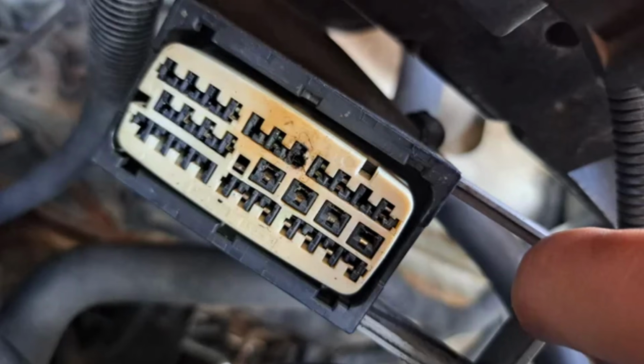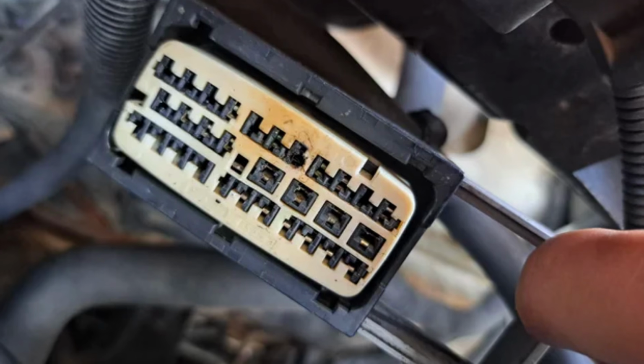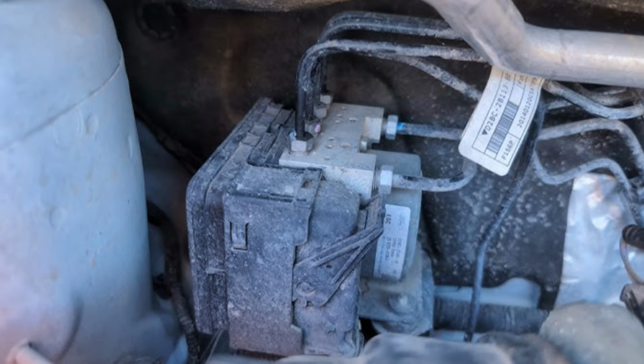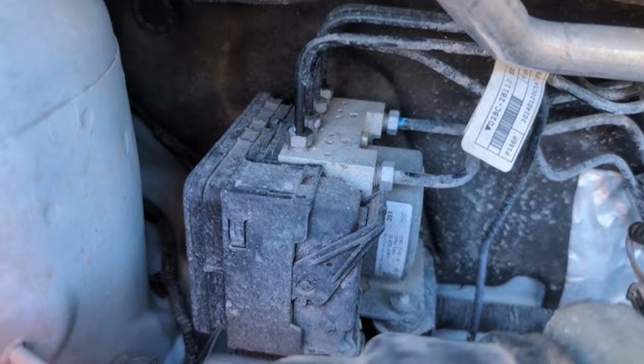Then it makes sense to have a look at the ABS module connector. Sometimes it may be loose or affected by water. Any corrosion on the pins means that you need to clean it properly or have a car electrician clean and check the system. Unfortunately, wiring may fail in other spots, like the wire connecting the ABS sensor with the module, or the harness connecting the ABS module with the PCM or ECU, etc. In such cases, you will need professional help to find the defective spot in the wiring.